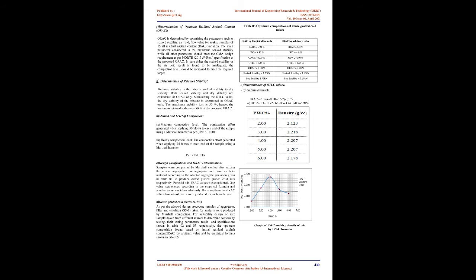D. Dry stability test and determination of optimum total liquid content at compaction, OTLC. Utilizing the IEC, the mix is compacted at the predetermined compaction level, 50 Marshall blows on each side of the sample. The loose mixtures are compacted at OPWC and then at pre-wetting water content, PWC, with 1% increasing steps from OPWC. The samples are kept for 1 day in their molds after compaction and thereafter extruded and kept for 1 day in an oven at 40 degrees C.